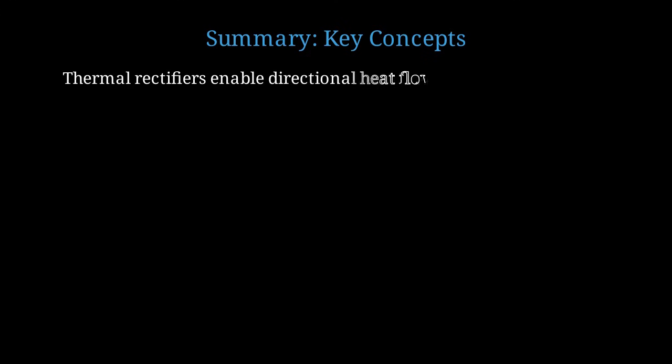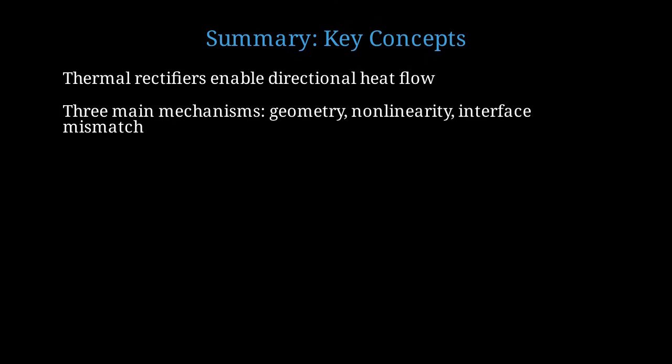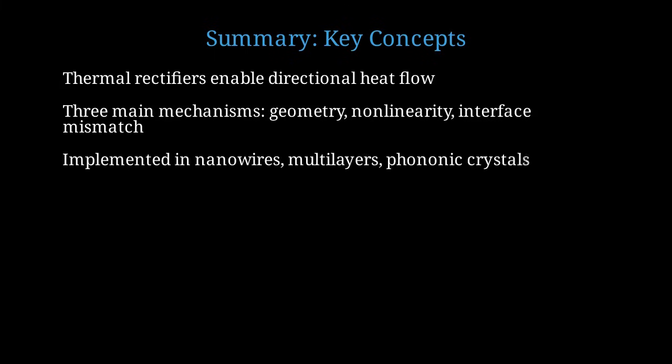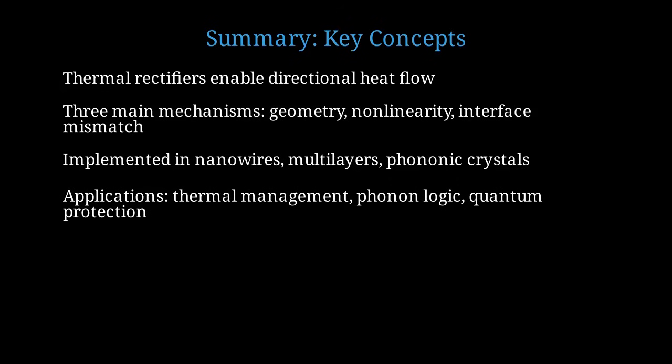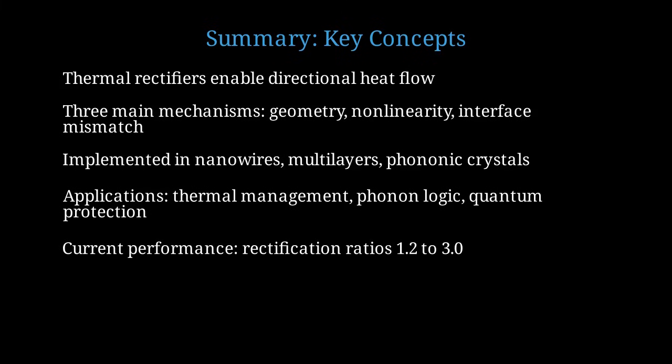Thermal rectifiers are solid-state devices that enable directional heat flow, analogous to electrical diodes. The three main mechanisms are geometric asymmetry, nonlinear lattice dynamics, and interface phonon spectrum mismatch. These principles are implemented in nanowires, multilayer structures, and phononic crystals. Applications include on-chip thermal management, phonon-based logic, and thermal protection of quantum devices. Current devices achieve rectification ratios between 1.2 and 3.0, with ongoing research pushing toward higher values.